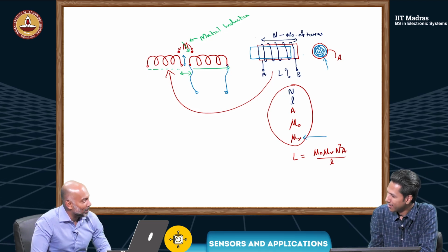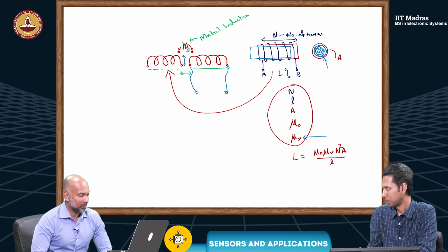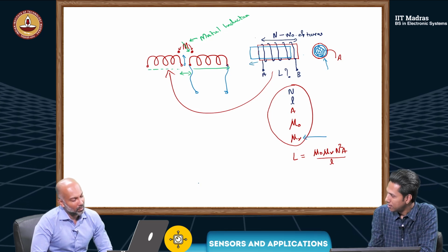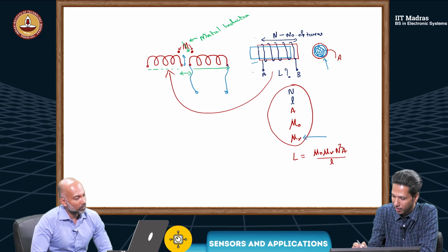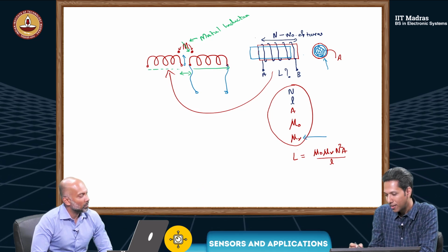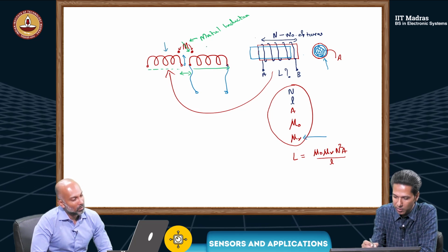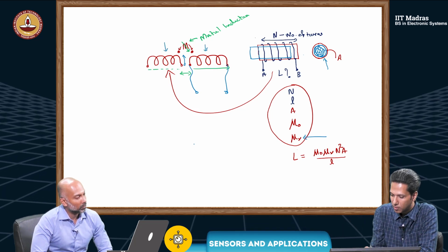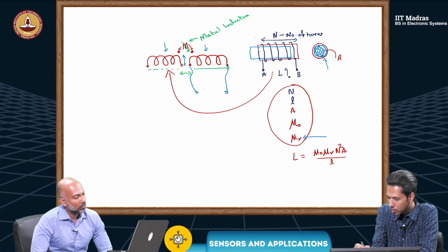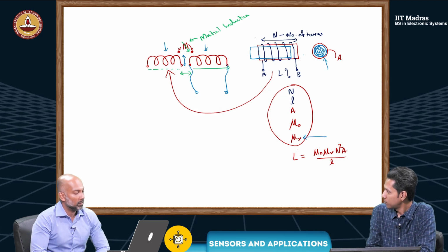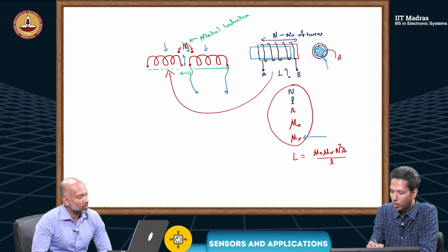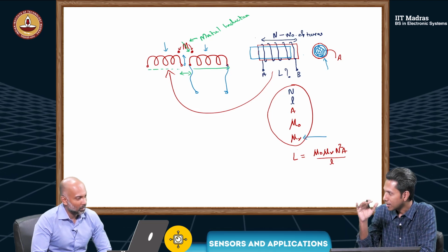So this is your movable member now. This is my movable member. Now, this is moved out of this, as per this drawing. So here I have two windings. The second winding can be close to it, such that when the member comes out, it can enter the other one, which is also possible. That way, I will have one inductance increasing and the other one decreasing.